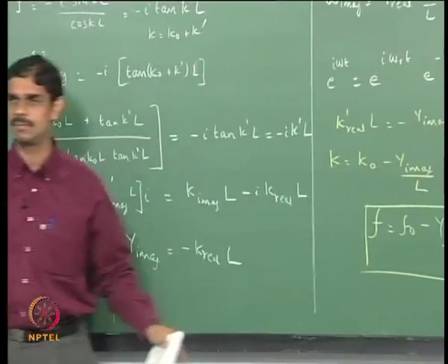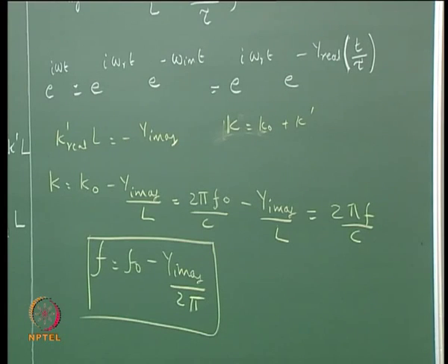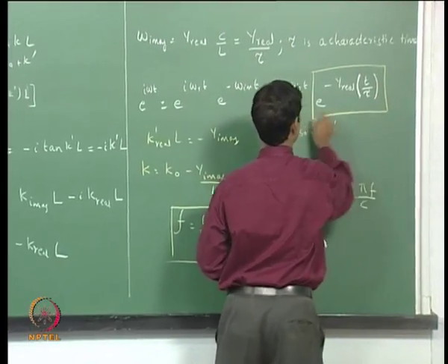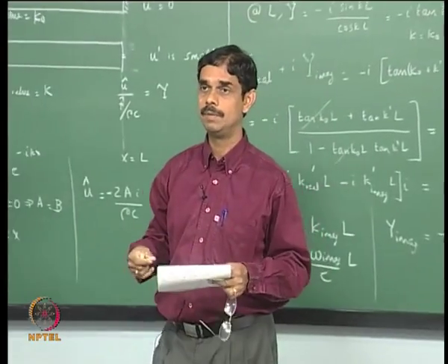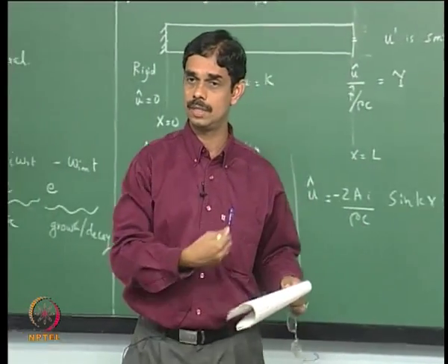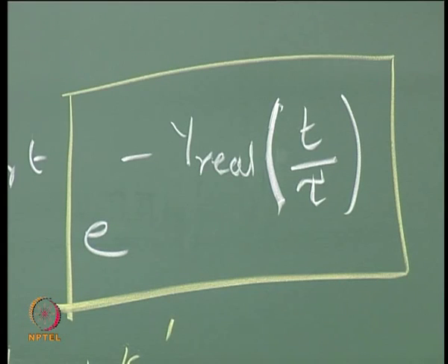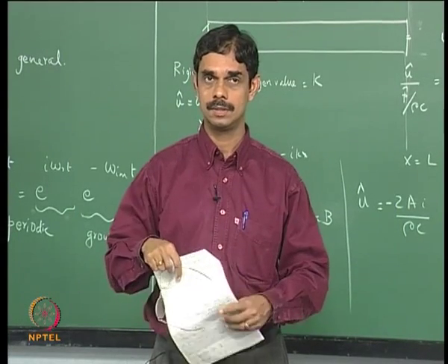So this is a concern in terms of what the actual frequency change is, but more importantly, if you speak about the growth rate, I think this term tells the whole story. So we can relate the impedance or the admittance of the boundary to whether the standing wave is growing in time or decaying in time. Okay, I think it's very straightforward. Any questions?